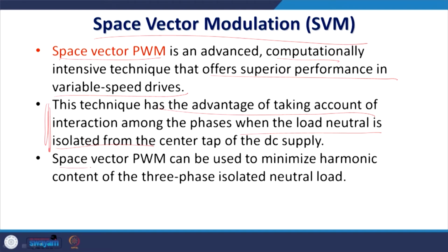Moreover, the space vector modulation technique can be used to minimize the harmonic content of the 3 phase isolated neutral loads, that is, for the 3 phase 3 wire system.